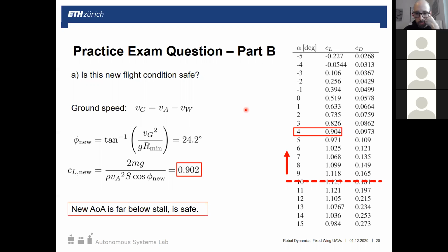Okay, so from Jan, why does the headwind decrease the ground speed? Assume headwind would add up to the relative wind velocity the airplane sees. So I'm glad if people post these questions, because it's good to clear these things up. We've defined wind in this lecture for the whole fixed wing part of it as the movement of the entire air mass, and we're defining it as steady, which means it's not changing, it's not varying, there's no transient, there's no force effects on the plane. It's only a velocity component that adds up to that final ground speed.